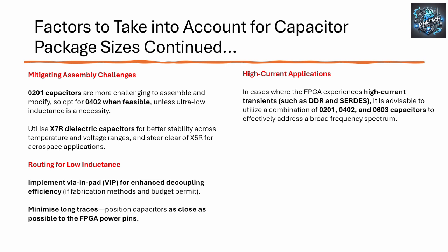This is just an extension of what I've just said. Don't use X5R capacitors. You can use wiring pad for enhanced decoupling technologies and so forth. It really depends on the cost break of your system, whether you're using blind and buried or so forth. If you're using blind and buried technology, you'll find that you'll have far more space underneath your BGA on the backside for all your decoupling. You'll probably fit a power supply underneath there. To be honest, I have done in the past many times.